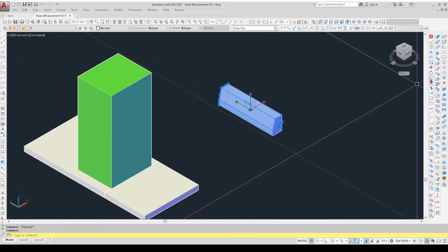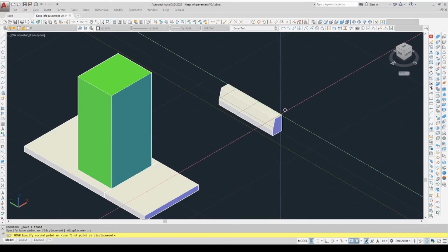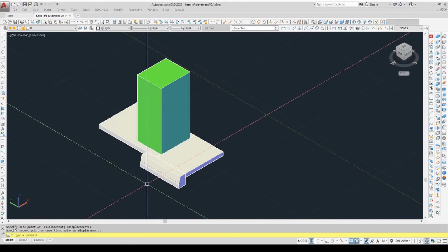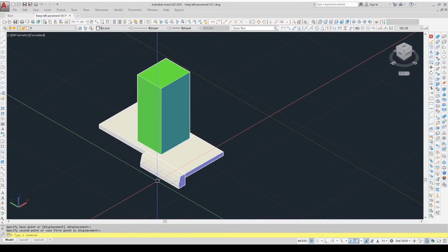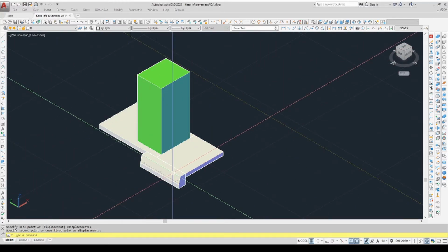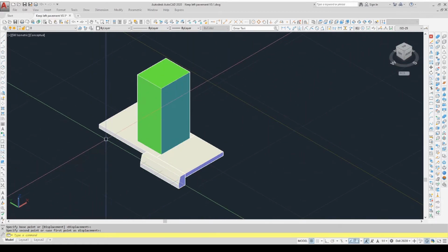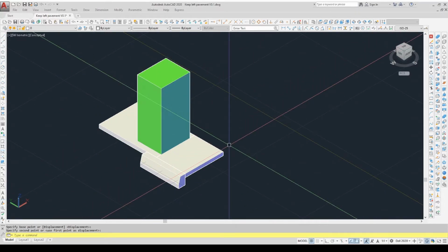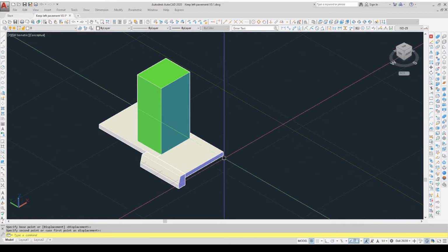We've now put it on its side, so I can now move that. I'll grab a corner, take it to this block, and we're beginning to get our curbing stones. Now, before I go placing them around, one of the aspects of CAD is that you can replicate things very, very quickly. So I could use a tool that would replicate that many times in a straight line, and then I could use another tool which would mirror that and put it on the other side.